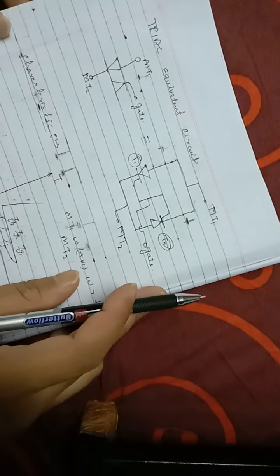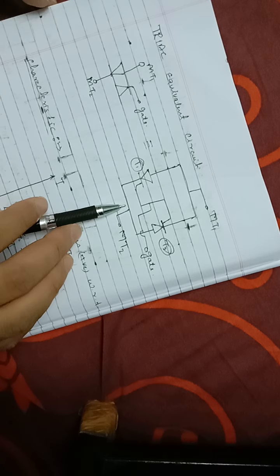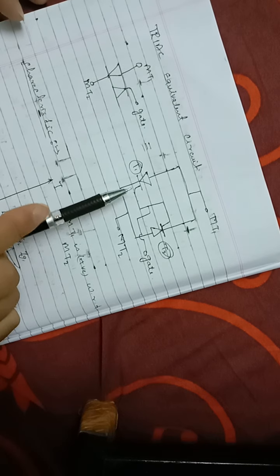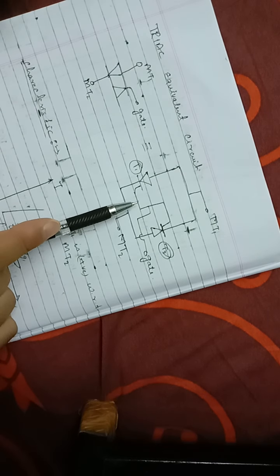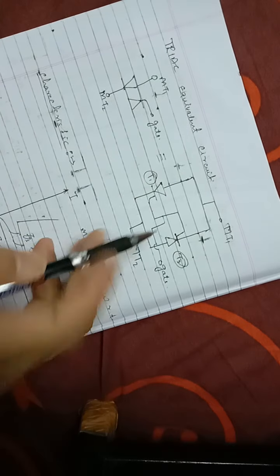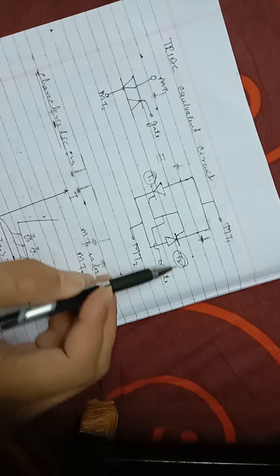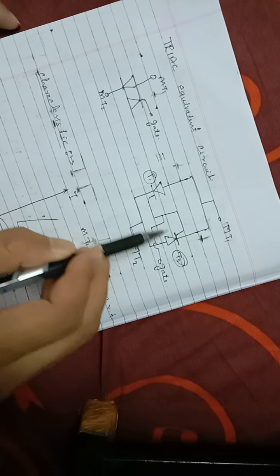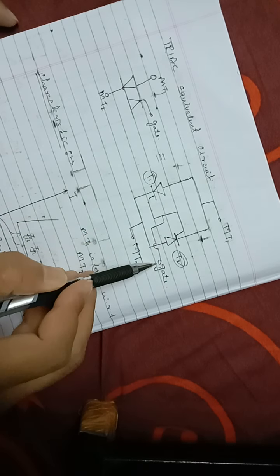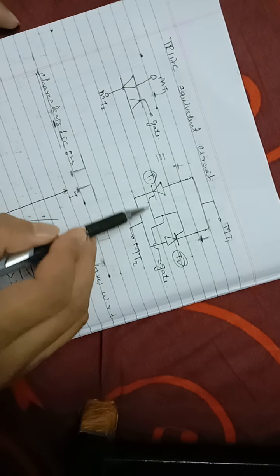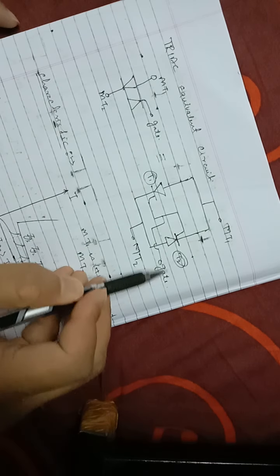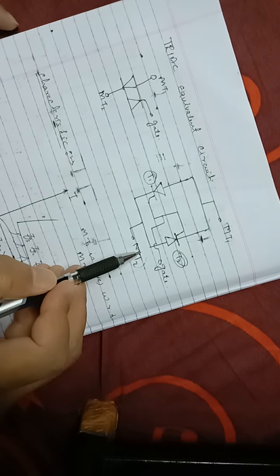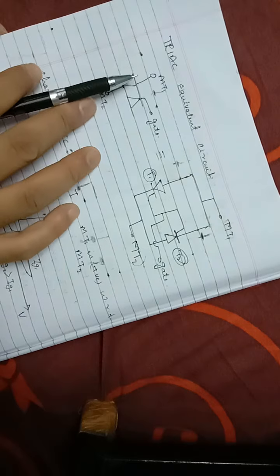You can say this is the physical analogy. If you want to see the two thyristor analogy, how it is connected in a practical scenario: here is thyristor 1, T1, and here is thyristor 2, T2. We take both gate signals and make them one. We combine the gate signal, and from that gate signal we control both thyristors. This is your MT1, this is your MT2. This is the TRIAC equivalent circuit.